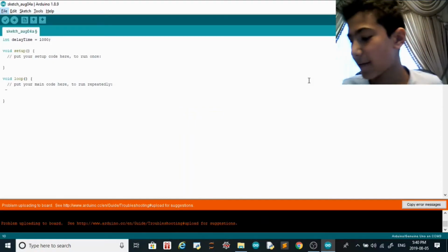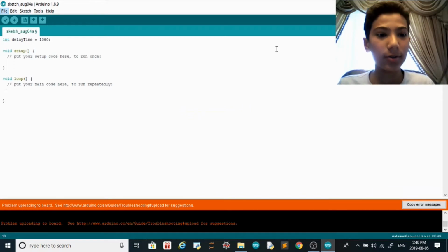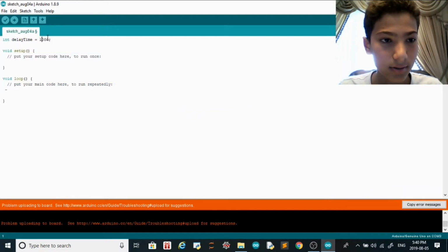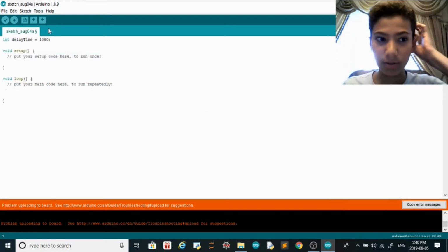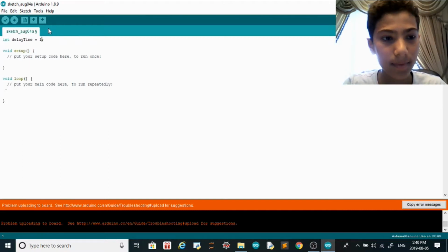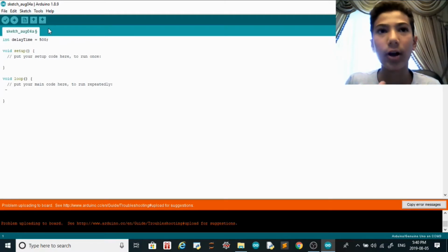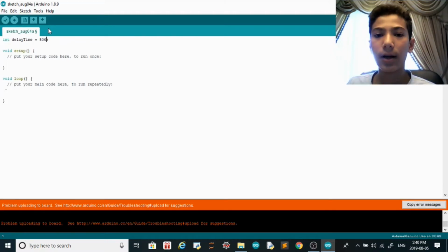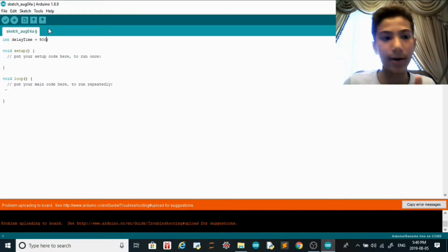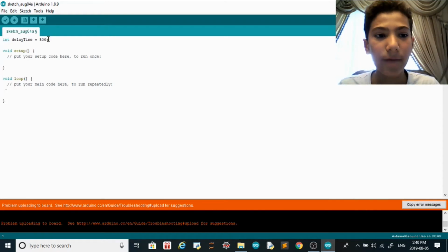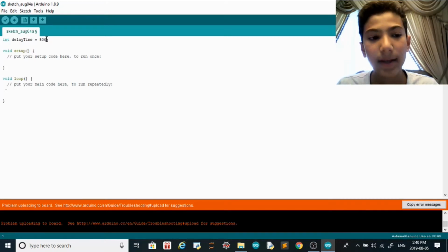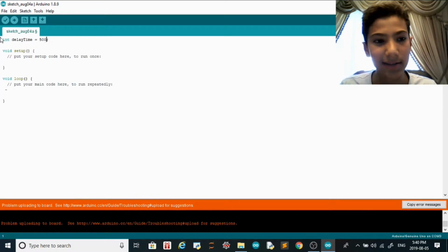Alright, so now that you have your hardware set up, I'm going to do the software. So just delete this. Oh, actually, I'm going to keep this. So delay time, I'm going to put it at 500. So it's going to turn on for half a second, and then turn off for half a second, so on and on. But by the way, it's 500 milliseconds we're talking. Delay is actually in milliseconds, not in seconds.